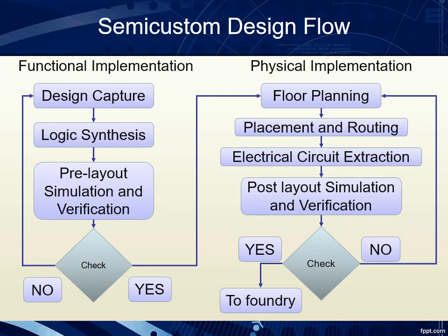Before doing the layout, when we have only the gate netlist, we perform a simulation at the level of the gate netlist in order to verify that the behavior is the same as the hardware description language based description of the circuit. We need to check that at the gate level, the circuit is behaving exactly as we want. If the check fails, or if there is a problem, the phase should be repeated until all the errors are addressed and cleared.